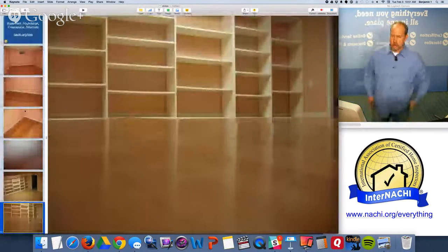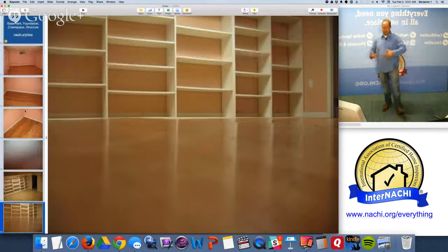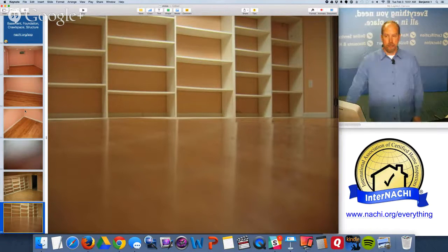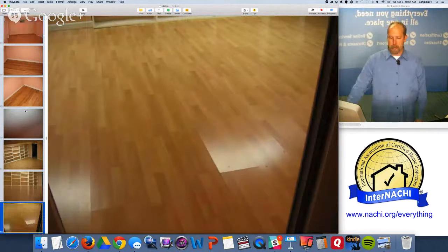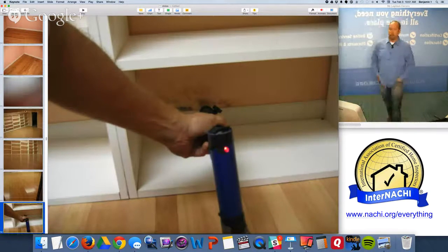And this floor actually had a bubble in the middle. The floor had paneling, flooring down, and there's a large bubble in the middle. Stepping on it, felt solid. I don't know why there was a big bubble. Something going on there, potentially. Not installed properly, or it was swelled. We may have water coming in. And we actually do. So that's me probing.